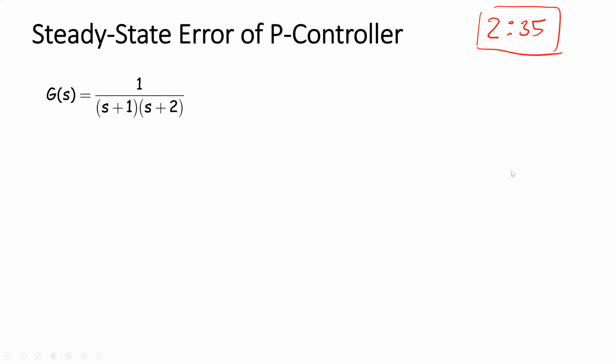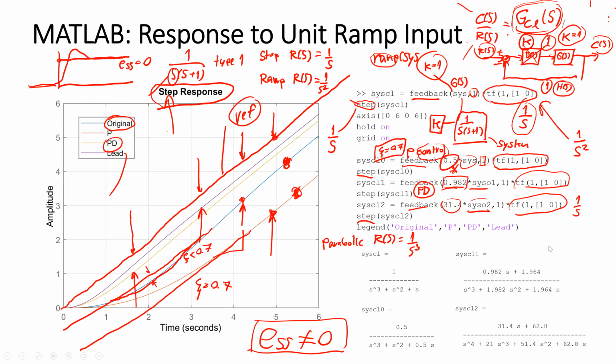So earlier in this class, we learned that with the lead compensator, we can use higher gain but still secure the damping ratio of the system, and it can provide a fast response but still not have overshoot. But the problem is, we still see the steady state error.